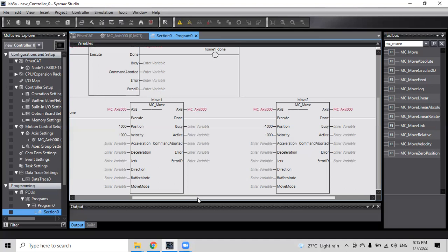And then you slow it down, right? Deceleration, decel. Where is jerk? Jerk is here. Jerk is here. You describe the change, the transient between one acceleration and another acceleration. That's why it's jerk. We have another name for it, smooth factor. Have you seen this before? No. Smooth factor describes how smooth it is between your acceleration and your cruising.